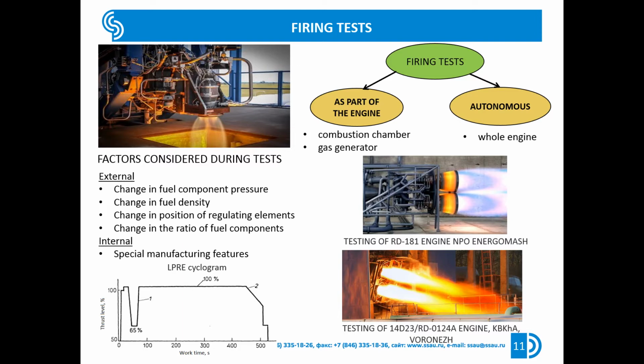Fire tests are carried out on the hot parts of the LPRE, the combustion chamber and the gas generator, as well as the entire engine. For the combustion chamber and the gas generator, autonomous fire tests can be carried out. These are usually conducted on special benches equipped with a fuel expulsion system. Such test benches provide a considerable amount of information. In these tests, combustion processes are analyzed, combustion stability is achieved, cooling modes are assessed, and the energy values are updated.